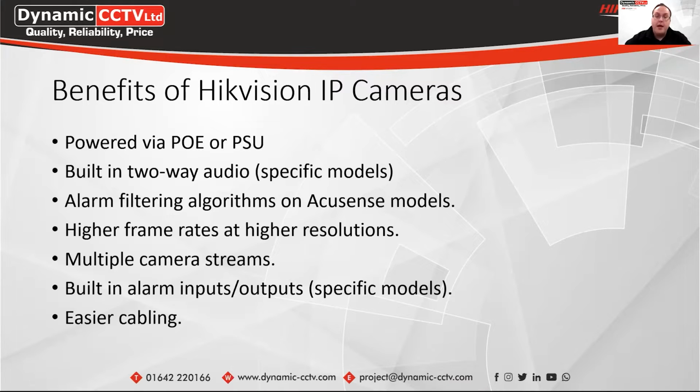You can also do the same thing with the audio outputs. So if you had a camera, say, in a warehouse, and you want to be able to speak out if someone's detected in that warehouse building, but you don't want to speak out across a full tannoy system, you could wire a speaker just to that audio output on the camera, and through either the Hik-Connect app or VMS platform software such as iVMS and HikCentral, you would then be able to speak out of that speaker that's wired to the camera.